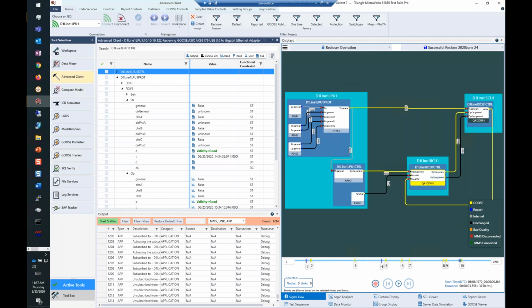And then once you get that basis there, you can right-click and get a context menu and see what other logical nodes this device subscribes to, and then click here and look at the other subscribers to this signal. So it's fairly easy to expand out the functionality that you're looking for to test.